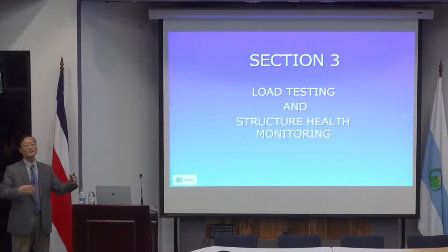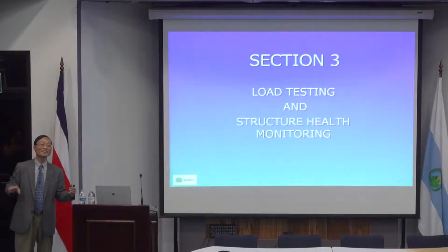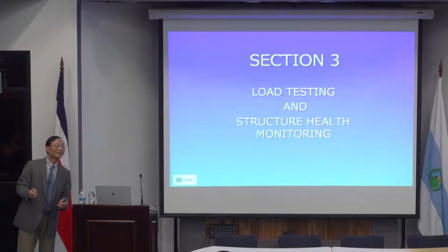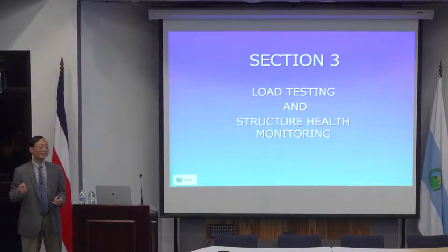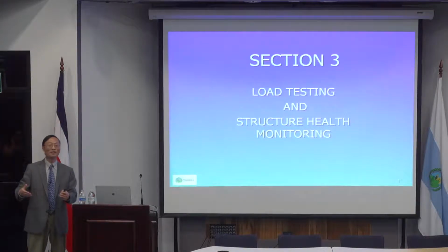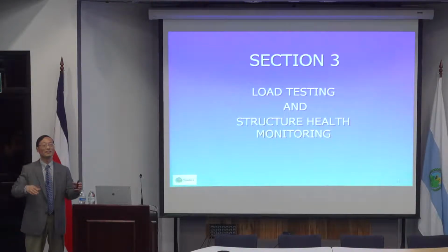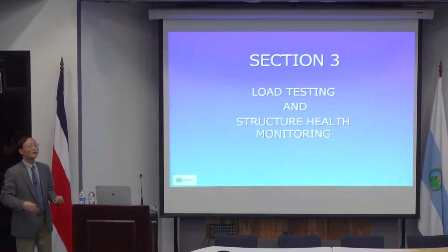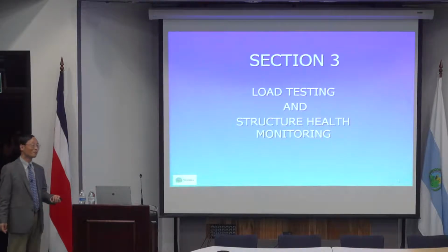Because the tests collect a lot of data, you cannot match all. You just use a mathematical equation, or visual inspection, basically trying to have the best fit. Once you have the best fit, that will be your model, and you can use that new model to calculate actual stress. And usually you will be able to achieve that goal.